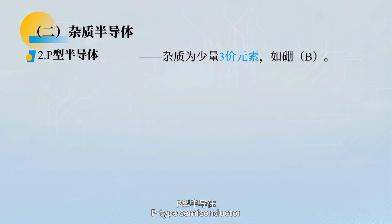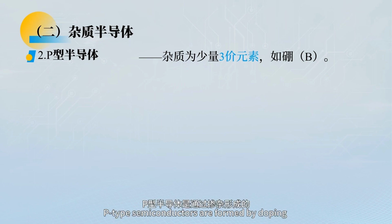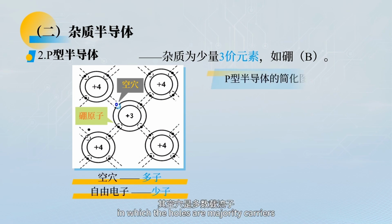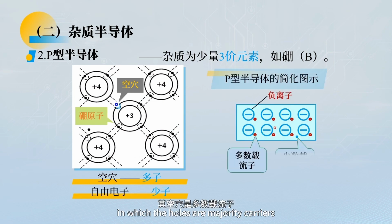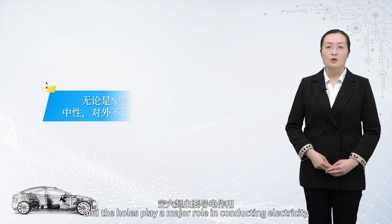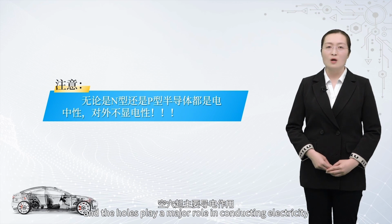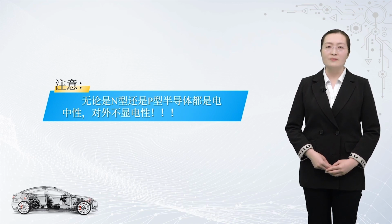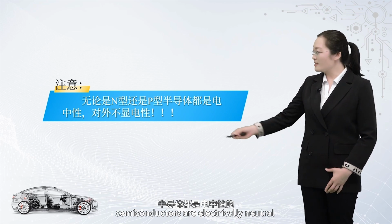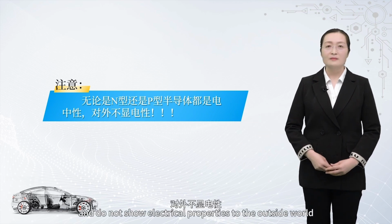P-type semiconductor. P-type semiconductors are formed by doping an intrinsic semiconductor with a 3-valent element, such as boron, in which the holes are majority carriers, and the free electrons are minority carriers, and the holes play a major role in conducting electricity. Please note that either N-type or P-type semiconductors are electrically neutral and do not show electrical properties to the outside world.